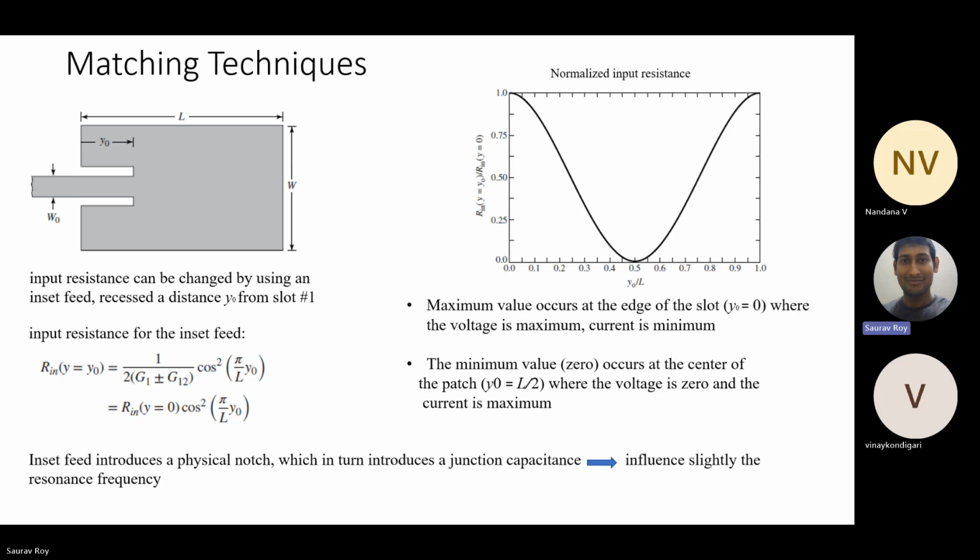Because of the length of the microstrip antenna, we have a lambda by 2 variation. So how is this a cos variation? It says the microstrip antenna acts like an open-ended circuit. So both radiating ends, radiating end 1 and radiating end 2, these two slots act like an open circuit. Open circuit means what?